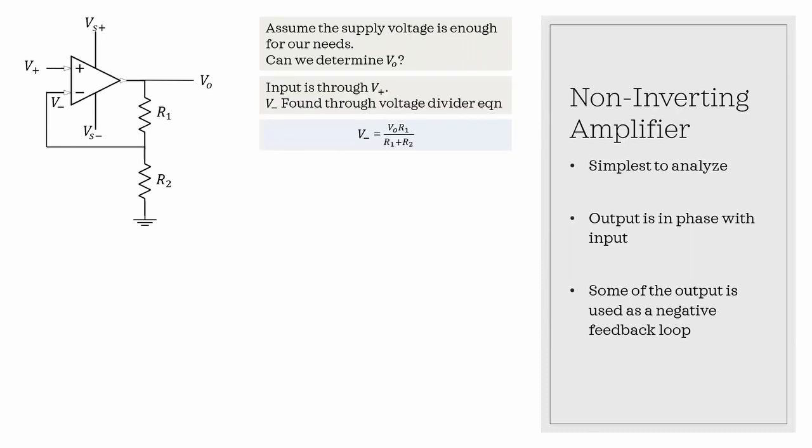First thing, we're going to use the voltage divider to determine the inverting input relative to output. And the non-inverting input is the signal and independent of everything else. And the reason we're feeding it back into the negative is, one, not only because it's negative feedback, but because remember the op-amp tries to get the voltage difference between the positive and negative terminals to be equal to 0 by modulating the output. So using the voltage divider here helps us regulate that so that we don't actually get back to 0, because we want to have some output.